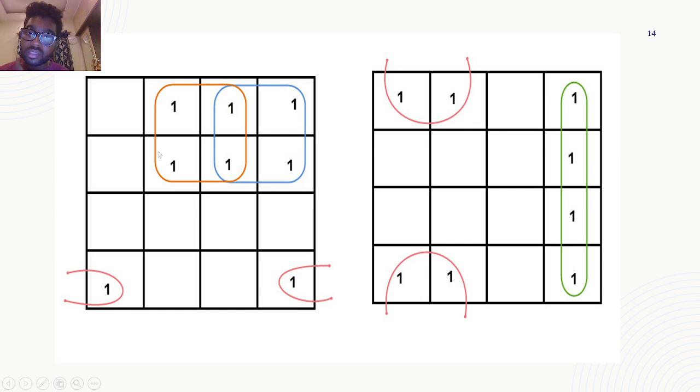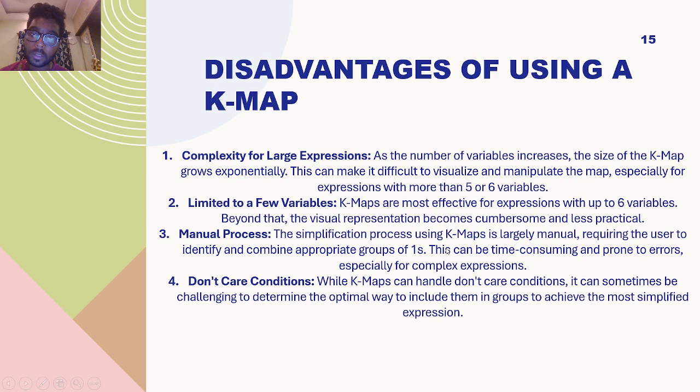When adjacent elements of the top of the K-map and bottom of the K-map are overlapping, this way we can group these two elements and these two elements. This is possible, and you can see here on the right side there's a 1, and in the left corner there's a 1. So by the paper folding technique, we can even group these two, and these two make a tuple, and these two make a four grouping.